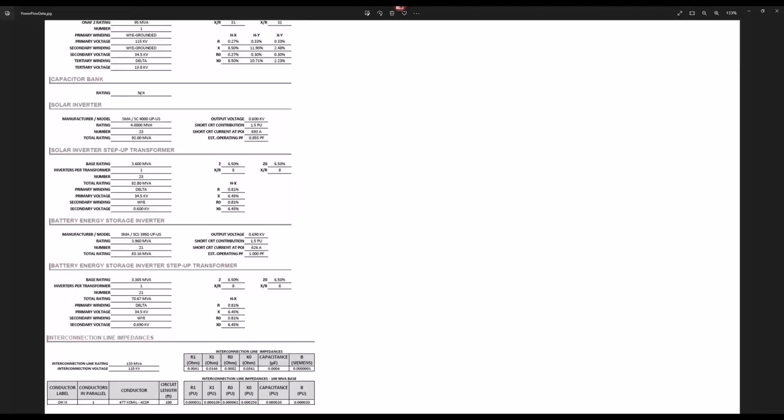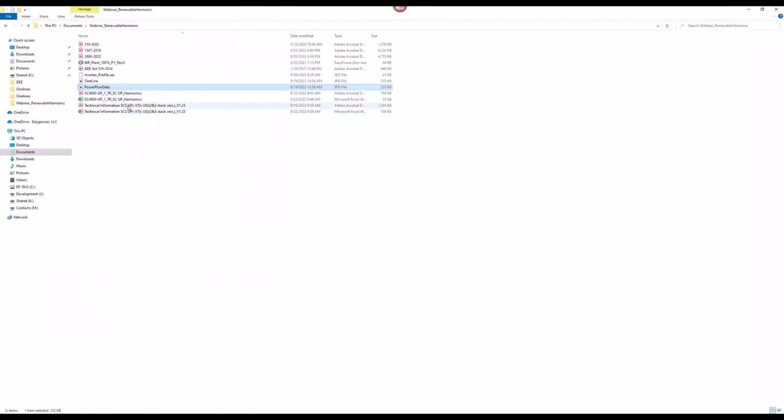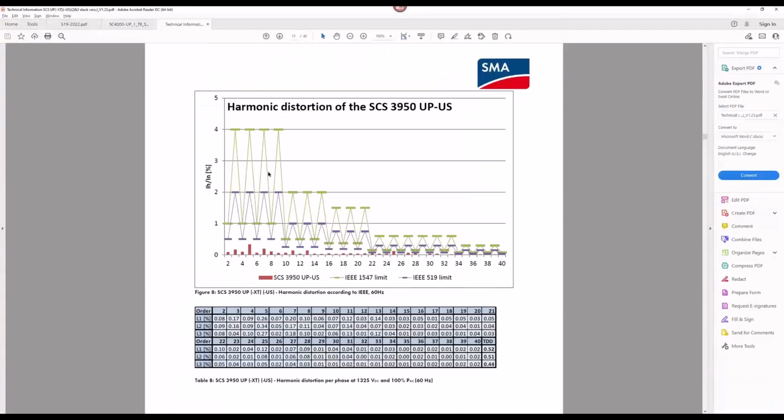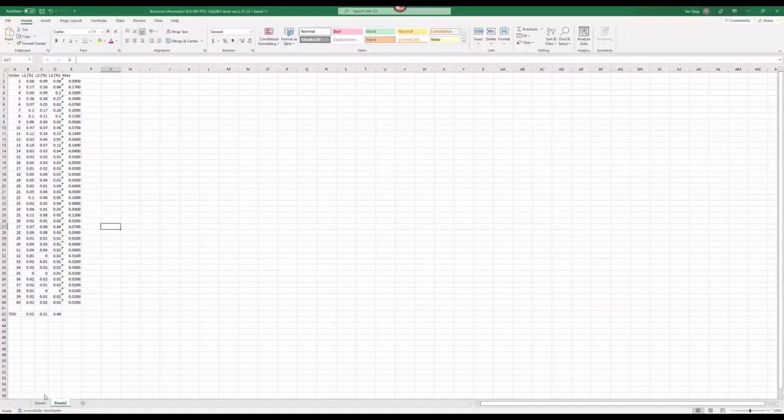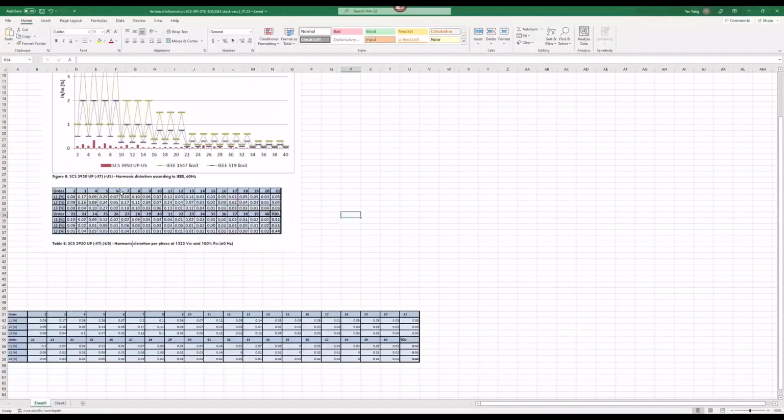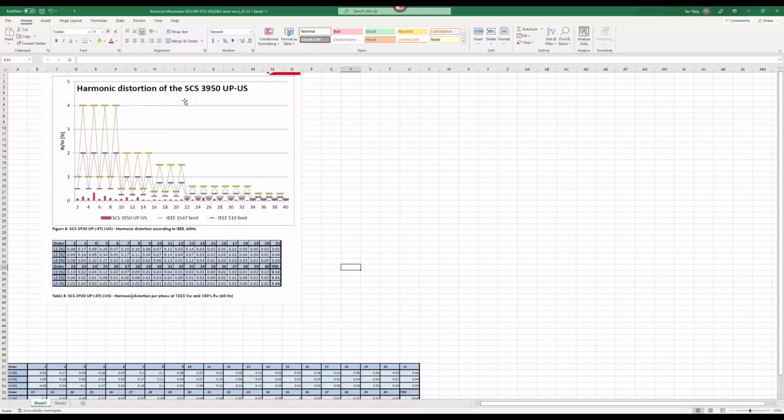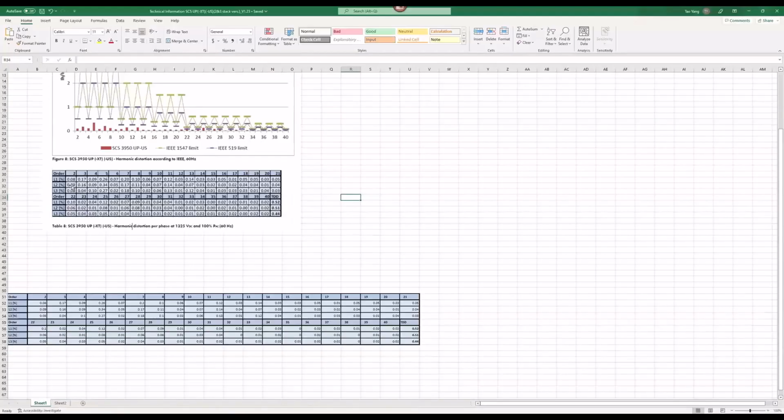At the very end, we are looking at energy storage, so you need to look at the energy storage portion of the harmonic current injection spectra listed in this way, right? And at the same time, it's just a working habit, I like to convert this whole table to an Excel spreadsheet. So I have the harmonic distortion of my energy storage inverter in this way, and because it provides phases A, B, C, what EasyPower takes is the positive sequence.